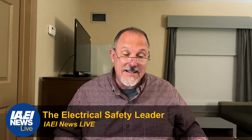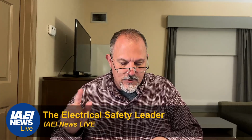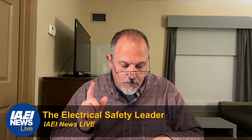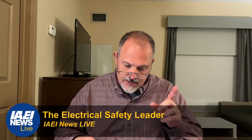Ground fault circuit interrupters. 680.22(A)(4) says ground fault circuit interrupter, GFCI, and special purpose GFCI protection. It says all receptacles rated 125 volts through 250 volts, 60 amps or less, located within 20 feet of the inside walls of a pool shall have GFCI protection complying with 680.5(B) or special purpose GFCI protection complying with 680.5(C).